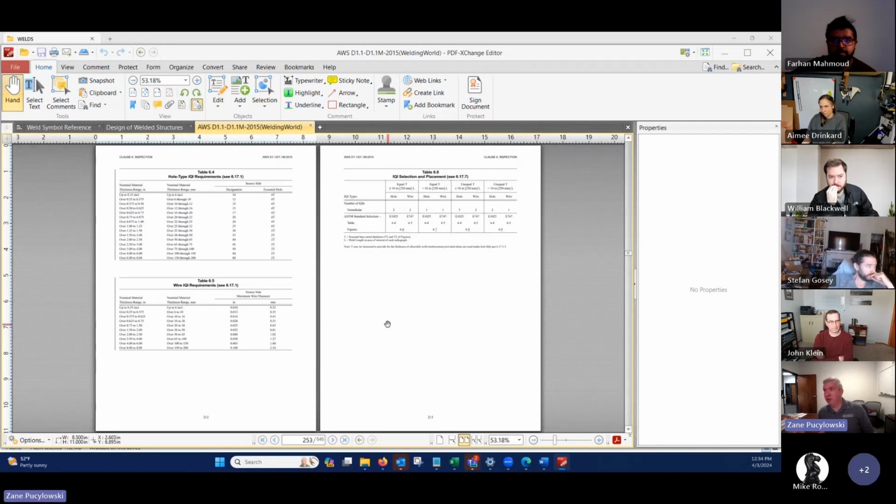Do they have to do NDT? If you require it. Remember earlier, the engineer had to tell if NDT was required or not. Sometimes you'll see me ask for someone to mag or UT a joint just to make sure I don't have any cracks in it, if it's something critical or hanging over somebody's head or it's going to be fatigue loading.